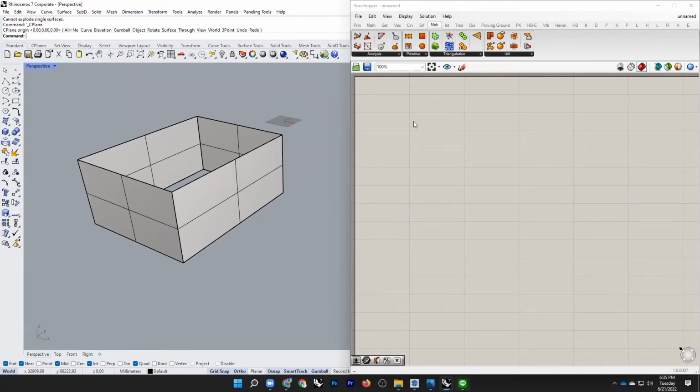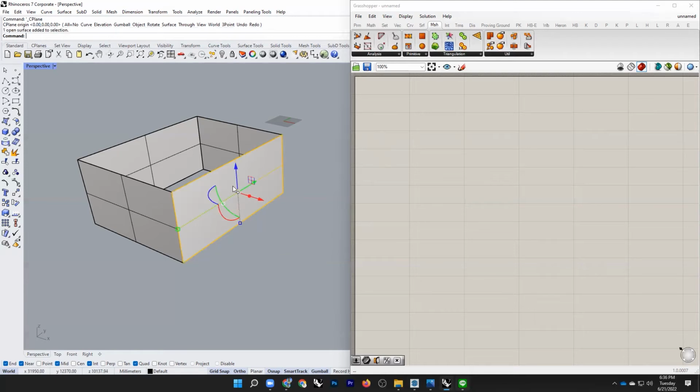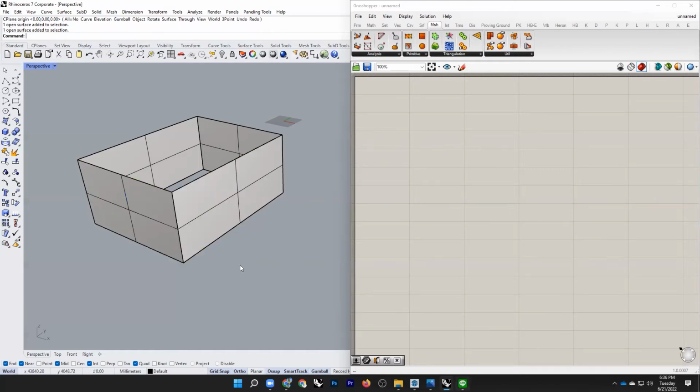And it's important that you need to learn both parts. You need to learn Rhino as well as Grasshopper if you want to work with Grasshopper. So when it's easier to make things in Rhino, you do it in Rhino. When it's useful to do it with Grasshopper, you do it in Grasshopper. So say I am trying to make a fenestration or facade on this wall, and it's easier for me to use Grasshopper. So I will bring this wall to Grasshopper.